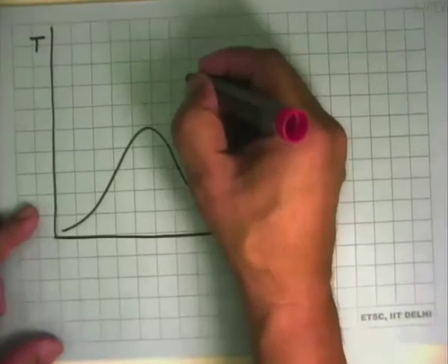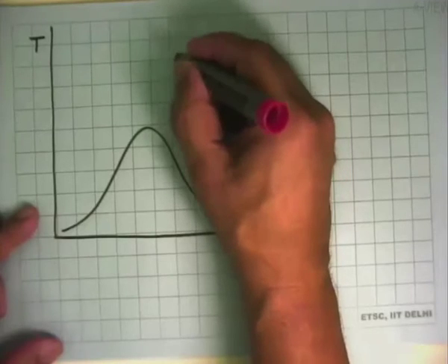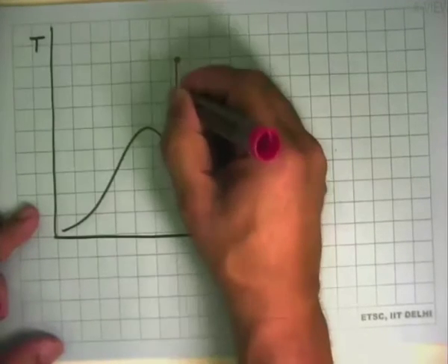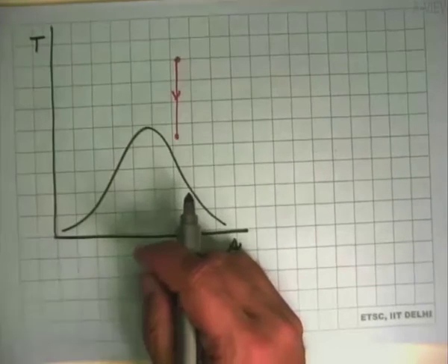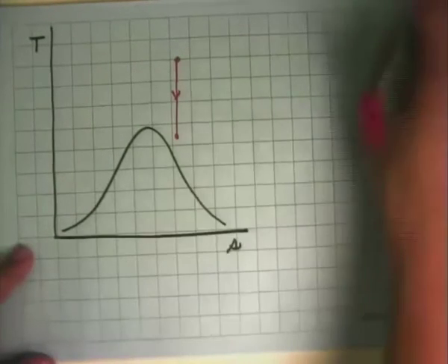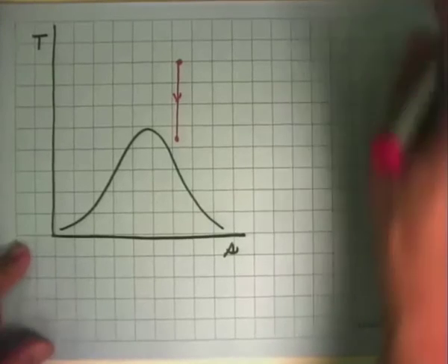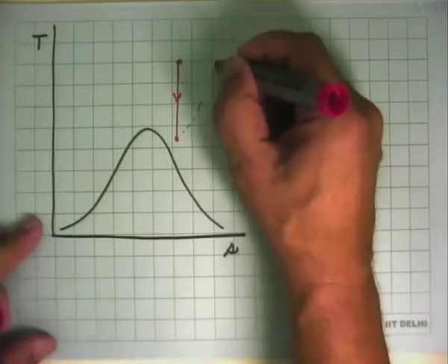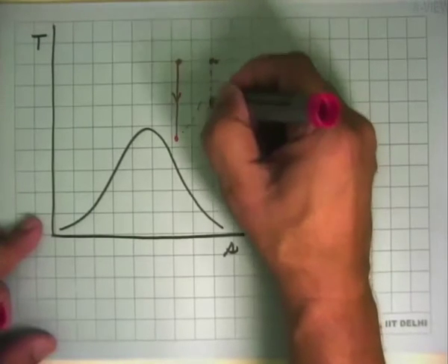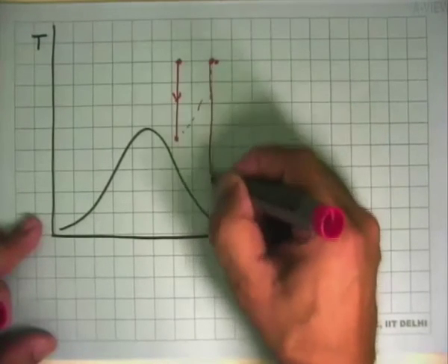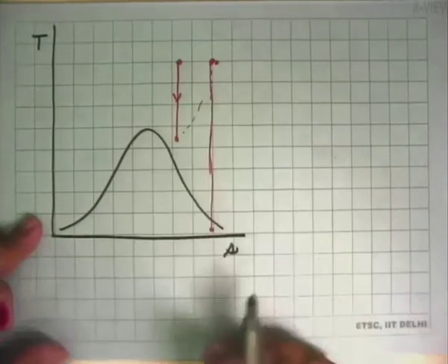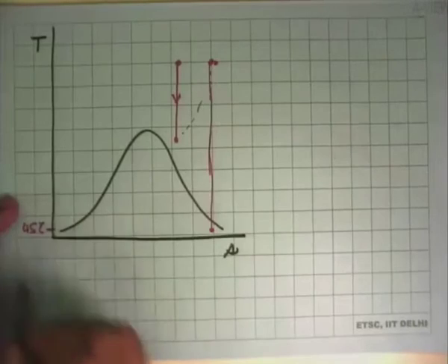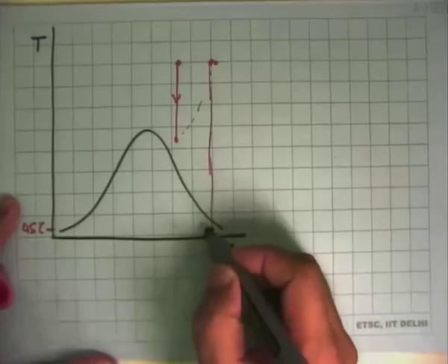So in power stations, we start off with superheated steam, expand it up to this point in one turbine, and then take the steam out and send it back to the boiler for heating again. Then we bring it back almost at constant pressure to the same temperature, and start expanding it in not just one turbine but multiple turbines until it reaches the temperature that is there for us, 45 degrees Celsius or so, slightly wet steam at the end of the turbine.